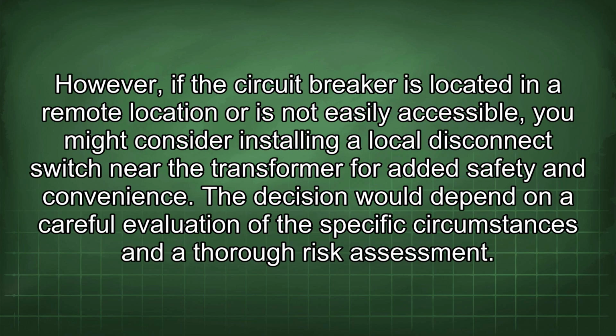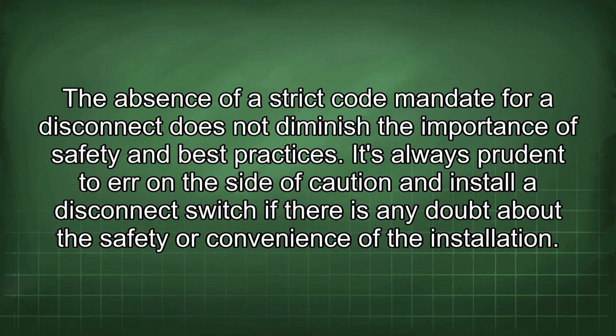However, if the circuit breaker is located in a remote location or is not easily accessible, you might consider installing a local disconnect switch near the transformer for added safety and convenience. The decision would depend on a careful evaluation of the specific circumstances and a thorough risk assessment. The absence of a strict code mandate for a disconnect does not diminish the importance of safety and best practices. It's always prudent to err on the side of caution and install a disconnect switch if there is any doubt about the safety or convenience of the installation.